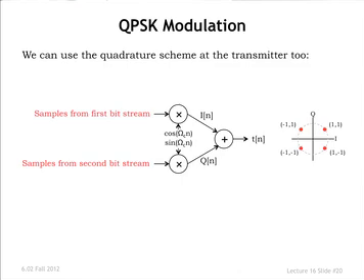At the receiving end, you multiply by cosine and then low-pass filter. That'll only pull out the first stream in the ideal case. Multiply by a sine and filter, you'll get exactly the second stream. So you can simultaneously send 2 streams on a given carrier using this method.